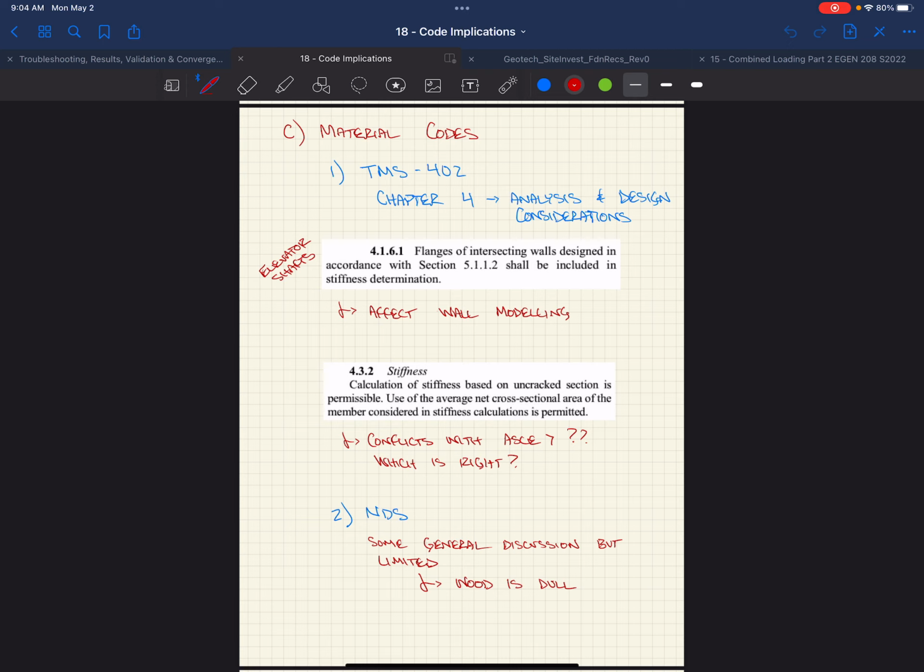For those of you that watched Matthew's presentation in steel, he talked very briefly about vibrations. In fact, you need to take vibrations into account. He mentioned some deflection requirements, which I don't necessarily agree with, but I wanted to highlight some things. There's a whole design guide for vibrations in steel design, Design Guide 11, a huge book that outlines the requirements for designing buildings for vibrations. So modeling for that becomes very critical, like monumental stairs.